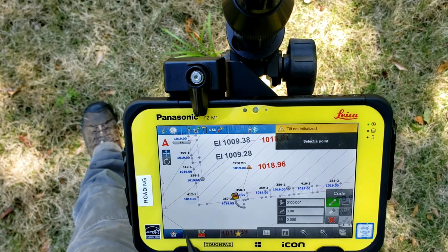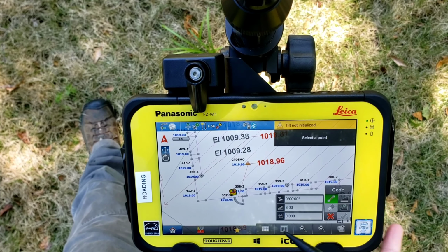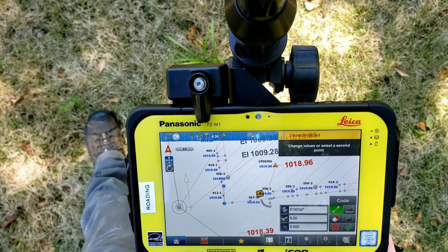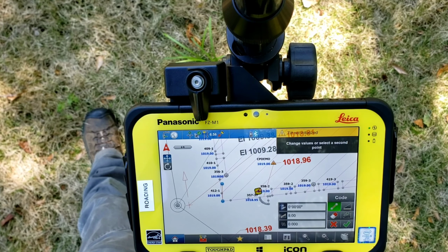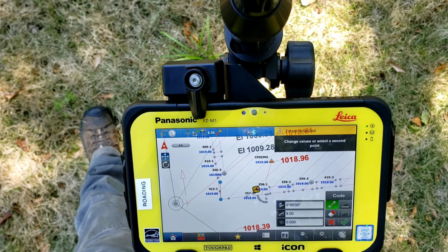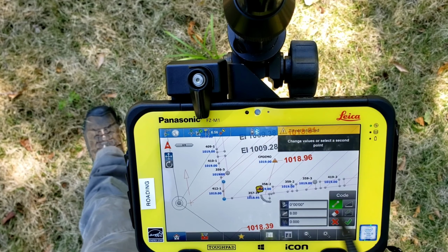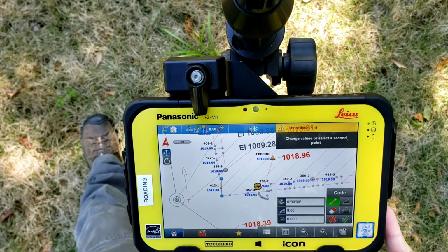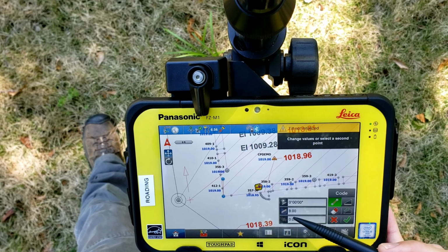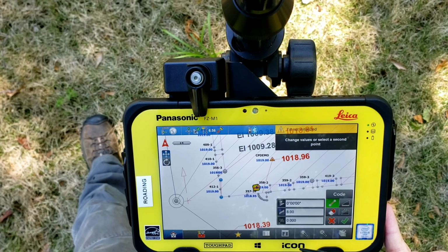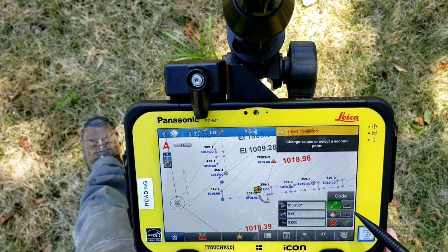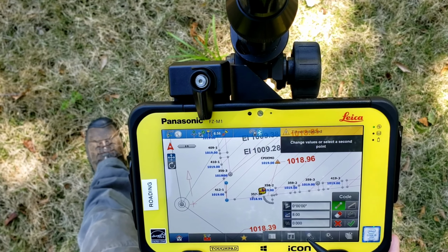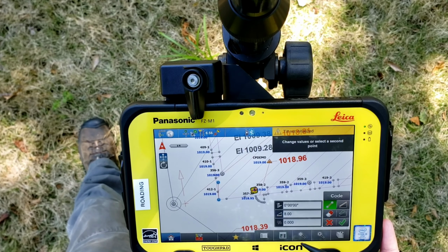Create point and line. This is also a killer one. So we'll just choose this building corner right here, just for simplicity again. So when I pick that point, and again, there's lots and lots of tools in here. Even when you pick this toolbox and you pick a tool, it brings you up other features here that you can utilize for your field work. So I picked that building corner point. It's going to default to due north. That's just your azimuth there. So obviously 0. This is going to be a slope distance of 8 feet. If you want to do a horizontal distance, right there you can see you got an orange line. It flattens it out. So this allows you to just do simple COGO in the stakeout menu.